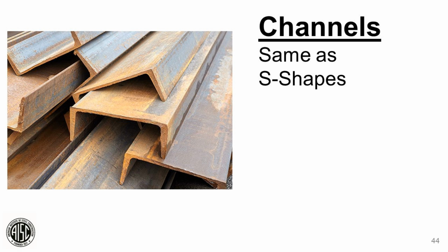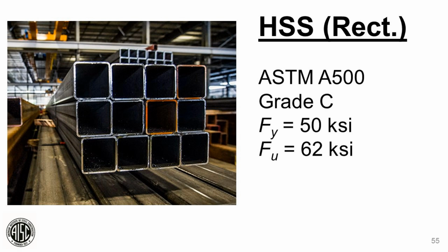Okay. There are a number of questions about the changing specifications for HSS. Can you explain, is there any difference in the tolerances for A500 Grade C as compared to Grade B? Or is it only the A1085 that has the different tolerances? Yeah, there is no difference in tolerances between A500 Grade B and A500 Grade C. A1085 has a tighter tolerance where you can use the true wall thickness.